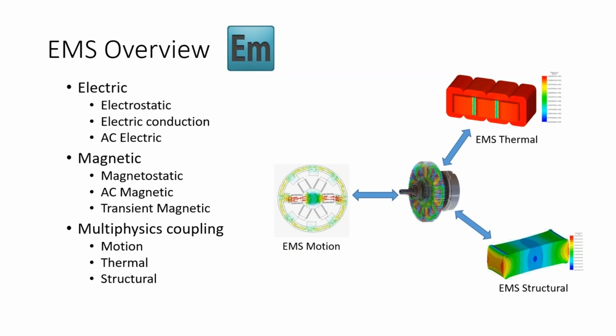The main applications of the electrostatic solver include analysis of voltage breakdowns at high voltage insulators, the electric stability and integrity between winding layers, etc. Whereas the magnetostatic solver is used for modeling of permanent magnets, permanent magnet machines, actuators, etc.